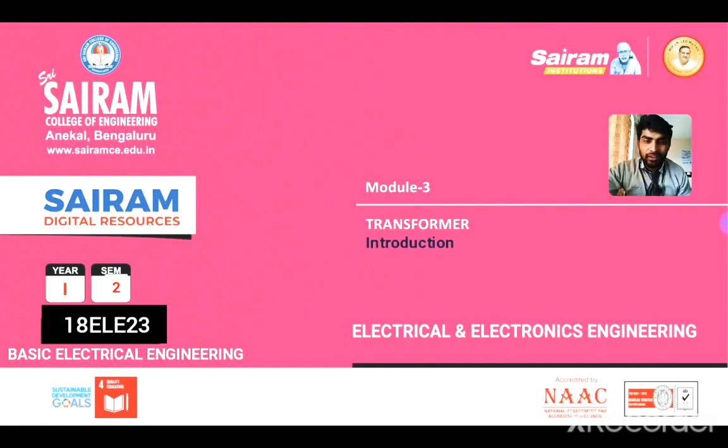Another best example I can give you: just find out nearby your surroundings there is an H pole mounted substation, or H pole mounted transformer. They place it in the shape of an H, right? That transformer converts 11 kilovolts into 230 volts plus or minus 5% tolerance, single phase, or 3 phase 440 volts plus or minus 5% tolerance, right?